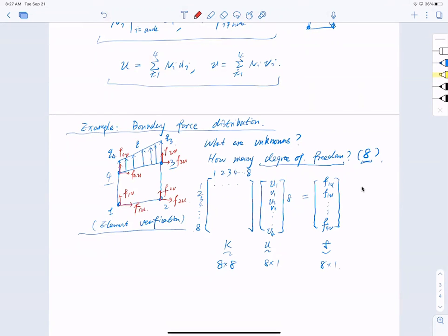Let me say it. I only see an element, the blue one, the original element. And I applied a blue distributed stress on one side of it. But I did not have any concentrated force on any of the nodes. So the answer is no, I don't have any nodal forces in this setting.